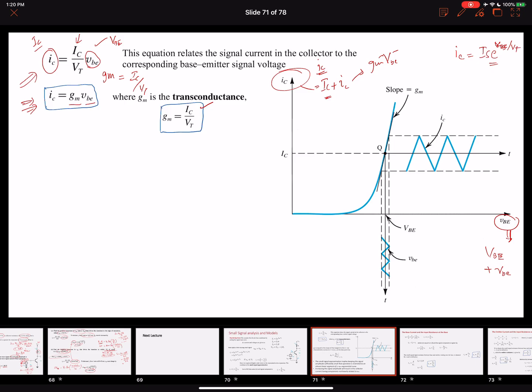Okay, so this is the exponential plot of the collector current to the input voltage. As we can see over here, if we select this quiescent point Q at this point, and then make a tangent here, let's look at the input and the outputs. We pick these points, and as our input signal varies, look at the changes in the output signal. Our output signal is amplified because of this exponential relationship. So this is our voltage controlled current amplification, right? So we have this kind of a transconductance amplifier. So we connect a resistor RC to get a voltage amplification.